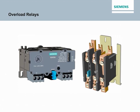Overload relays are designed to meet the special protective needs of motors. Overload relays continue to provide power during the short duration overloads that occur when a motor starts. If an overload condition persists, however, the overload relay removes power from the motor. Once the overload condition has been corrected, the overload relay can be reset to allow the motor to be restarted.